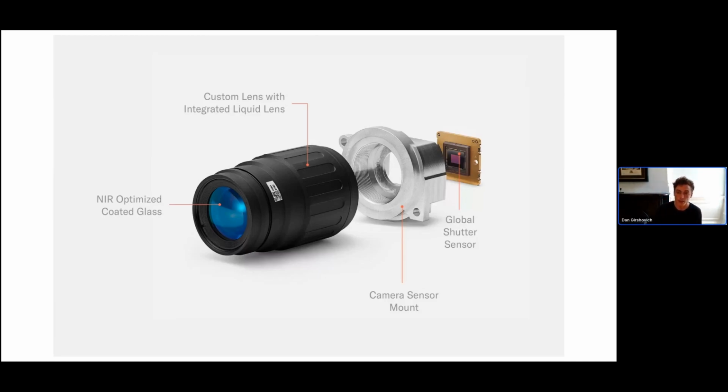This is the lens that I mentioned. I have it here because it is one of the more interesting parts of the device, because it was custom tailored, if you will, for the orb to achieve as high iris quality as we can get for this use case, which is relevant for the distance that users are from the device, and the fact that we don't know that distance, so it has to quickly change its focus and track the user's eye. Interestingly, it's a liquid lens, so that means there's actually a piece of liquid in there that is actuated to change its shape, and that helps achieve the requirements that I described.